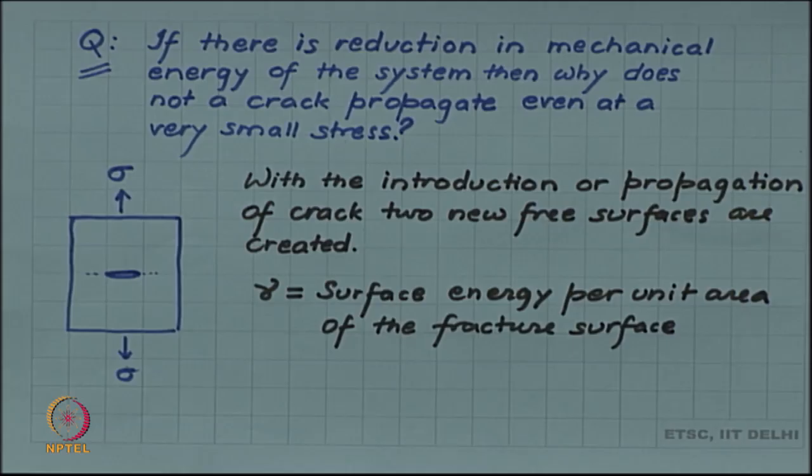So, this is a very interesting concept. This is a novel concept. This was a novel concept at the time of Griffith. Before Griffith, no one had realized this and nobody had introduced this into the analysis of fracture. So, it is of central importance to Griffith's analysis that he introduced the concept of surface energy of the fractured surface into the analysis of crack propagation.